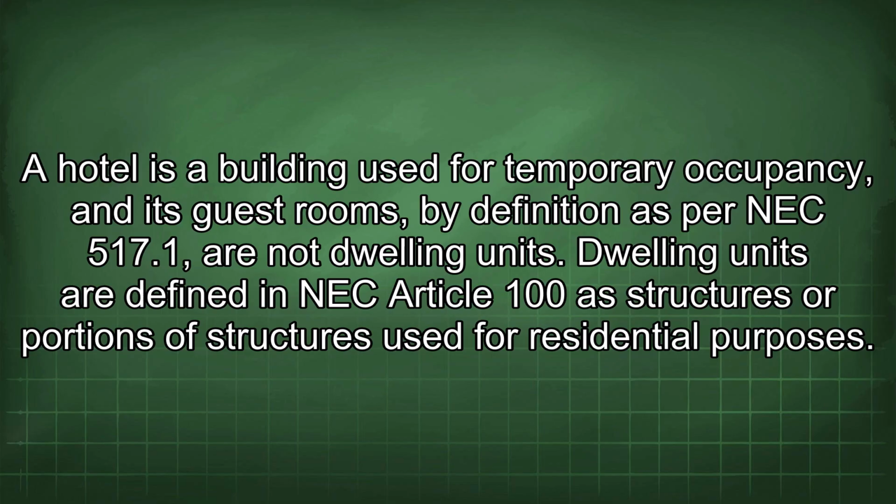A hotel is a building used for temporary occupancy, and its guest rooms, by definition as per NEC 517.1, are not dwelling units. Dwelling units are defined in NEC Article 100 as structures or portions of structures used for residential purposes.